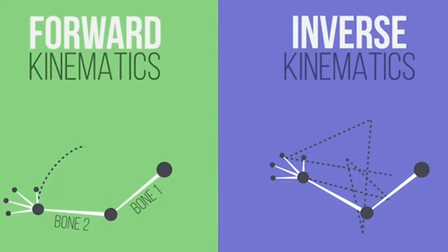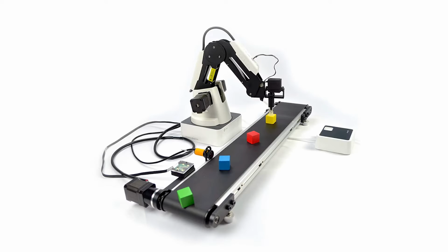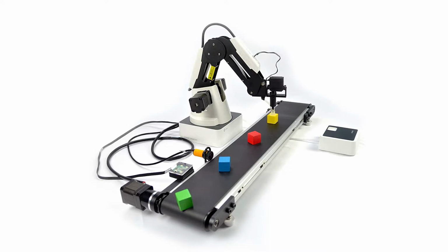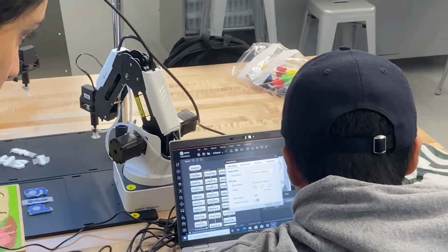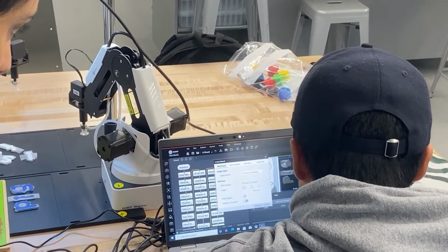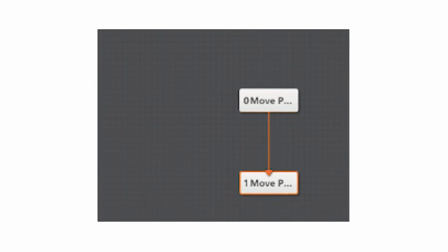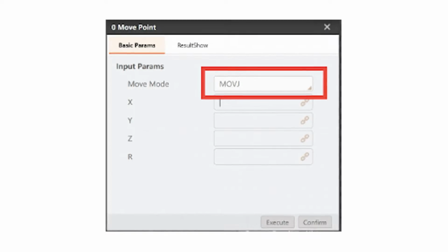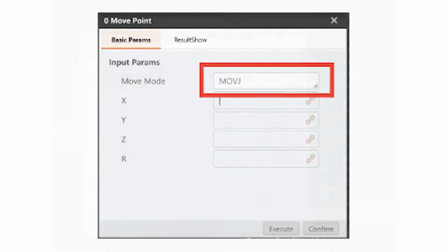In the second lab, our team worked with a physical robot arm called a Dobot Magician and explored its functionalities. The team first explored the coding software for the Dobot, which would utilize simple drag and drop blocks with connective arrows to dictate the logical flow of the code. The team used this code to move the robot from different positions using movement point commands.